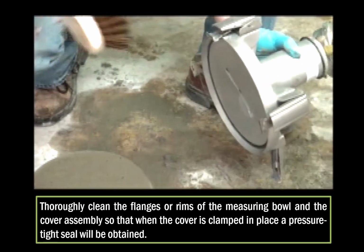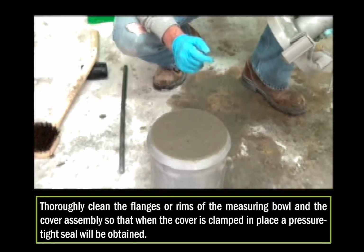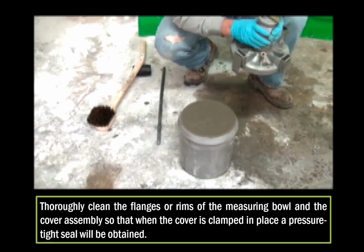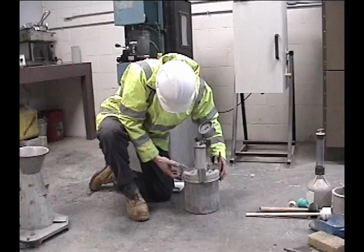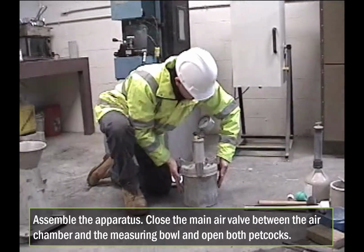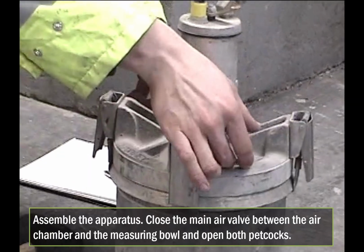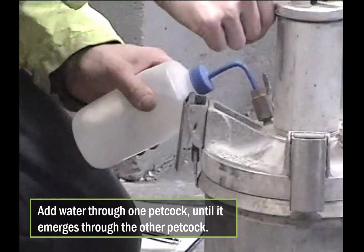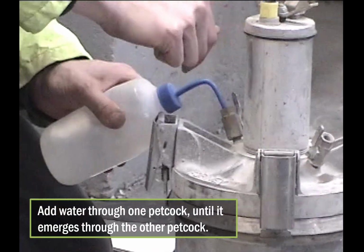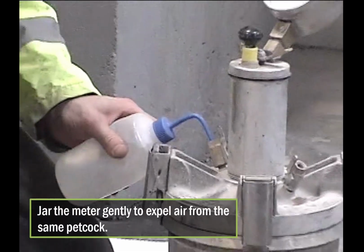After strike-off, thoroughly clean the flanges or rims of the measuring bowl and the cover assembly so that when the cover is clamped in place, a pressure-tight seal will be obtained. Assemble the apparatus. Close the main air valve between the air chamber and the measuring bowl, and open both petcocks. Add water through one petcock until water emerges from the opposite petcock. Jar the meter gently until all air is expelled from this same petcock.